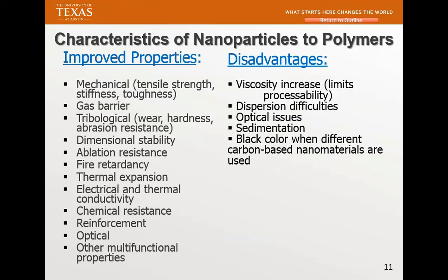The same thing works for thermoplastic. You put it in the twin screw, and suddenly, Dr. Kathy talked to me the day before, and he's putting all these in there, and the machine is not cranking because it creates another torque. It may break the twin screw. So that's what you see in some of these, what you call viscosity increase. If the viscosity increases so high, you cannot even turn the twin screw. You may break the twin screw. And that's what you need to watch out for.